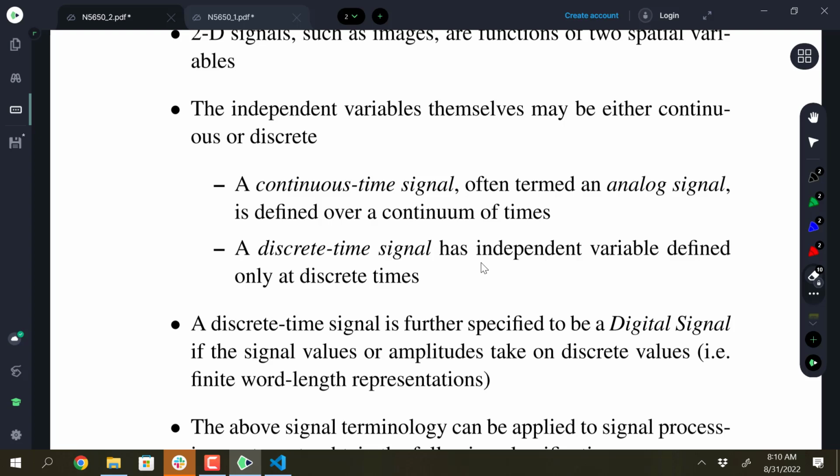So it's going from a purely mechanical means, air past my vocal cords, all the way into your eardrum, and then it becomes a signal that arrives at your brain. In my recording now, it's still a sound pressure wave, but there's a transducer in the microphone which converts that to a continuous time signal, and then there's an analog to digital converter running inside my laptop, which converts that to a discrete time one-dimensional signal.